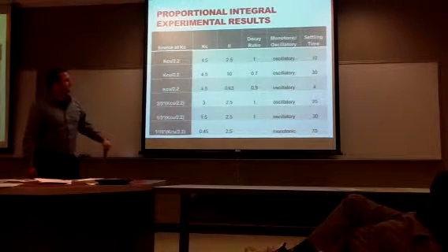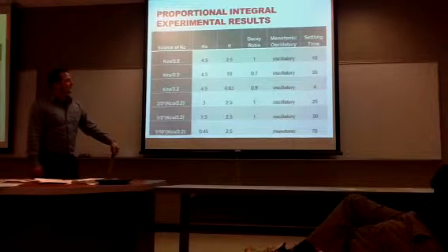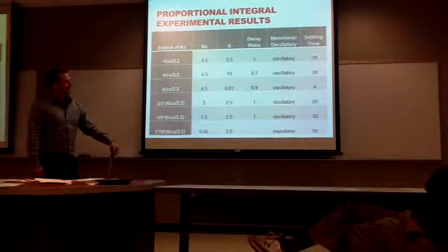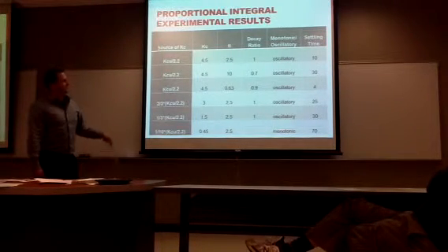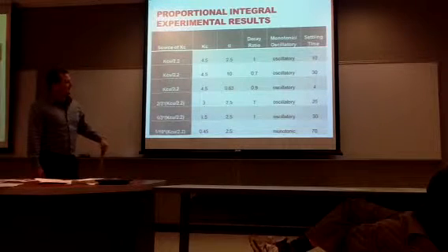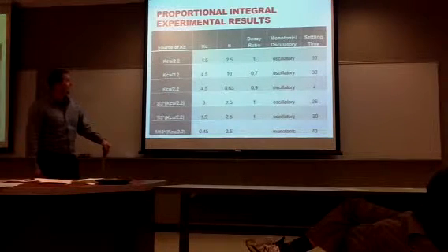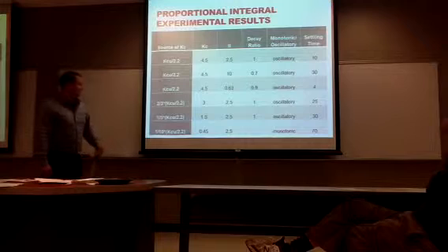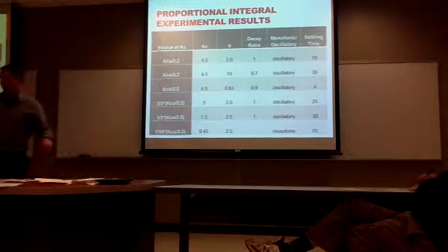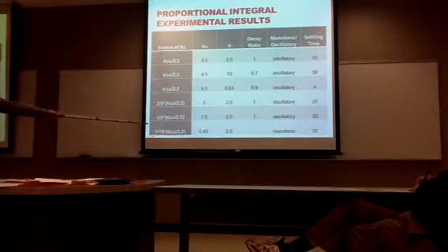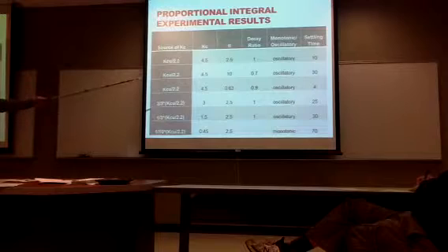I didn't notice much difference in the decay ratio, and I didn't really see much of a pattern in the settling times either. You can note that the one that was monotonic took 70 seconds, compared to the one that took just 4 seconds at 4.5 and 0.63.